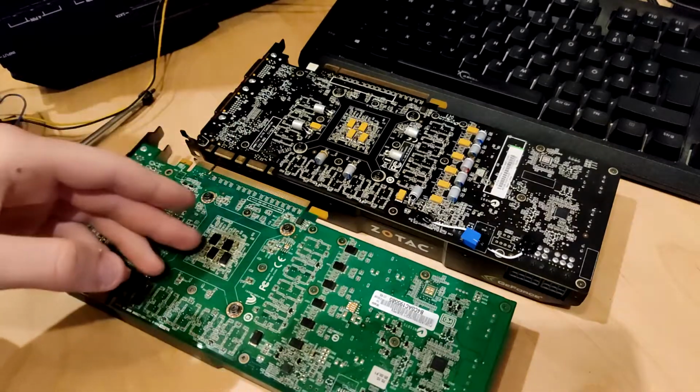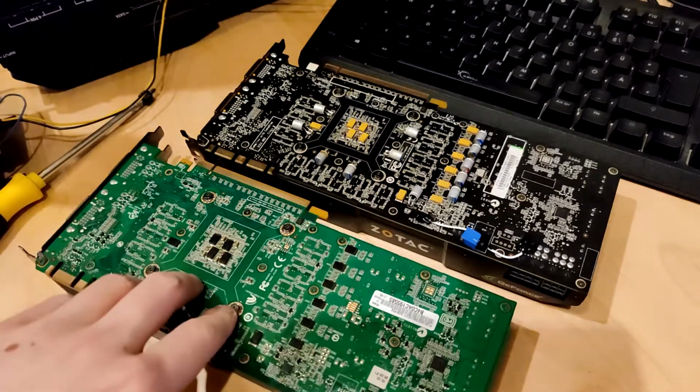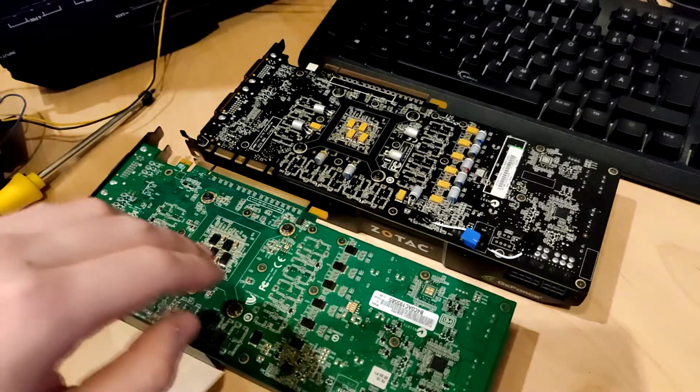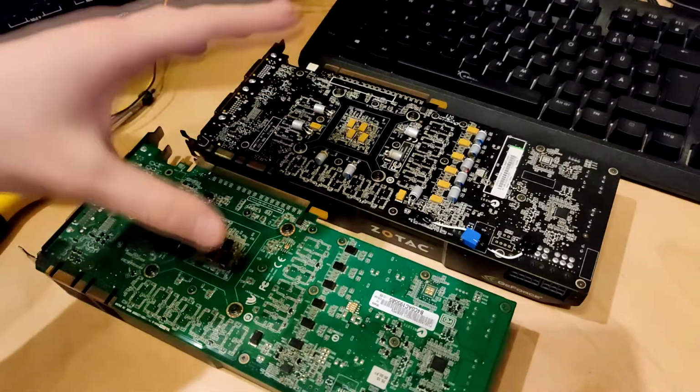Silicon lottery describes how every piece of modern silicon, what your core and your memory is made of, is slightly different, because the manufacturing process is so small. Modern Ryzen 3rd Gen CPUs have transistors that are only 7 nanometers large. These older cards are still at 40 nanometer, but 40 nanometer is still very tiny. And so these huge, very complex, highly developed chips, you literally can't make them without some kind of imperfections. Because of these imperfections, every single chip, be it the exact same one, both of these cards have the same GF110 chip in them.